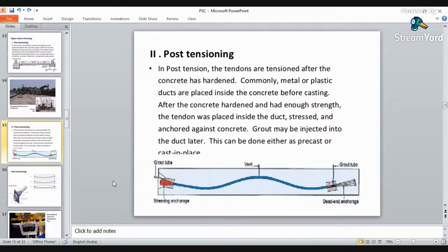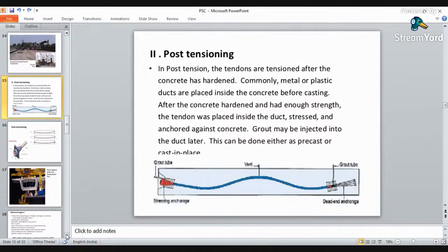So for this operation, first we need the casting of concrete. Okay, a concrete will be cast, then there will be placement of the tendons. The tendon will be placed, then there will be anchorage block on both sides. On both sides you have to place the anchorage blocks. Then you have to apply the tension to the tendons. The tendons will be pulled from both sides by using the anchorages. Then there are wedges which will be applied before the cutting of tendons, and once the wedges are fixed, then there will be a cutting of tendon.